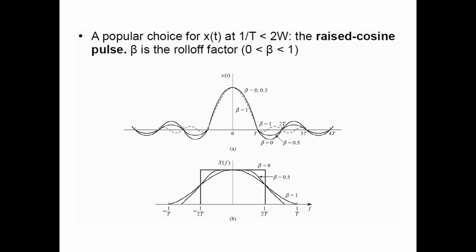But the point is that in practical scenarios, this is the condition when the channel is not time varying. But in actual circumstances, the channel varies with time. The channel is not constant. The channel is varying randomly. In that case, even if you have designed a pulse for the particular channel condition, since the channel is time varying, you will have to adaptively design the pulse shape to bring the ISI to zero.